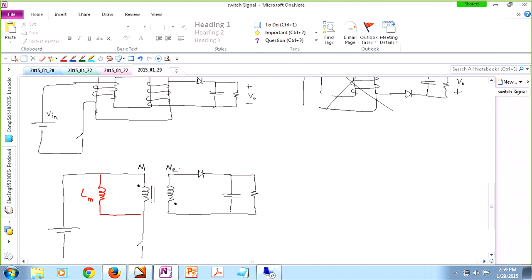Okay. So we are going to label a bunch of things, like this is the input current, obviously. And now we have one inductor in our system, so mystery solved. This is the primary side voltage, V1. Secondary side voltage, V2. Pay attention to the dots. On the secondary side, because of the orientation of my winding, actually the dotted node is down there. So the dot is not actually connected to the dotted node. It is connected to the undotted node, basically. What else? So we have a switch over here. We have a diode over here. And obviously you know the rest of the parameters.